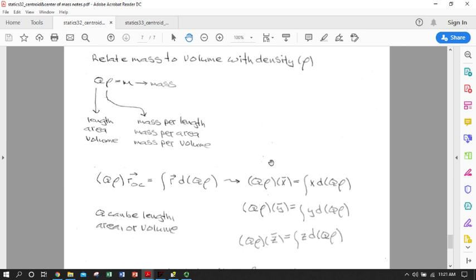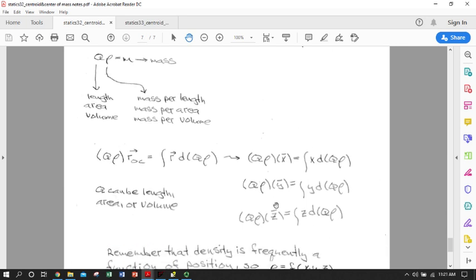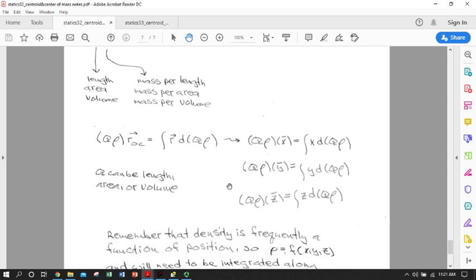So this would be the procedure you'd use if you had a continuously varying density. If you had discrete density parts, like a steel part welded to an aluminum part, you could use the method of composite parts, using each part's specific density to define its own center of mass and then add up the centers of mass.